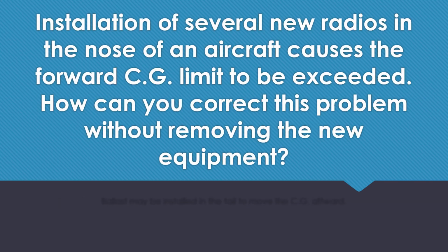Installation of several new radios in the nose of an aircraft causes the forward center of gravity limit to be exceeded. How can you correct this problem without removing the new equipment? Ballast may be installed in the tail in order to move the center of gravity aftward.